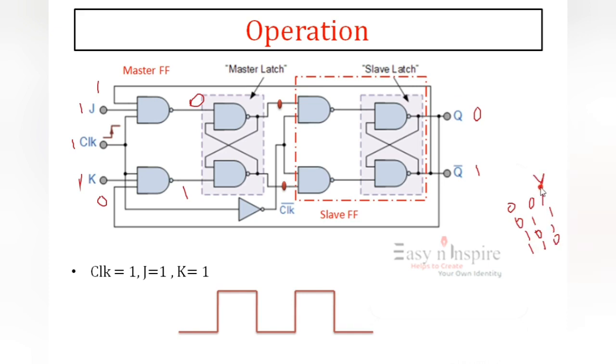This is my output. So if the first input is 0, whatever the other input may be, it results in 1. So 1 here I am placing. And 1 and 1 becomes 0. We have already discussed all this. So 1, 0 are going to this second circuit. But here the clock is 0, so it is deactivated.